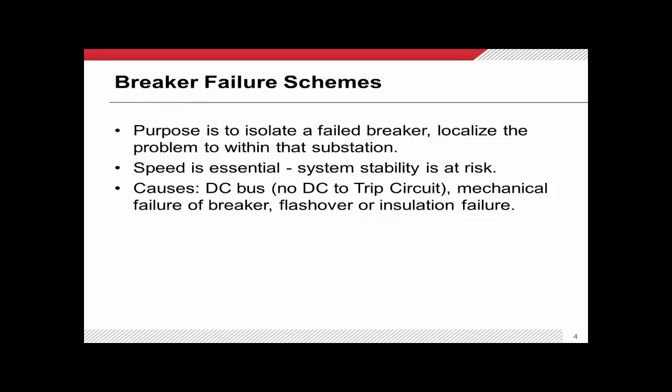going to work. You can also have mechanical failures within the breaker, say a pole, something breaks and a pole actually does not, the interrupter doesn't actually get moved when you try and trip the breaker. You can also have insulation failures within the circuit breaker, and if the insulation fails, well, you can do all you want with the interrupter, and it's really going to have very little effect.